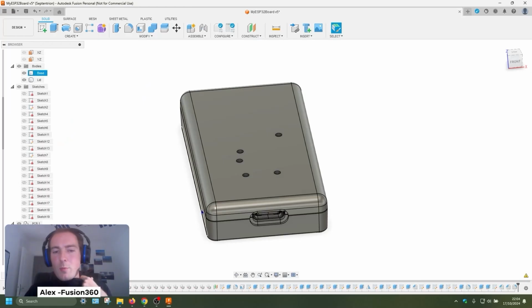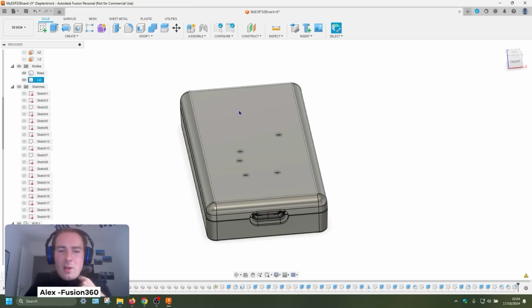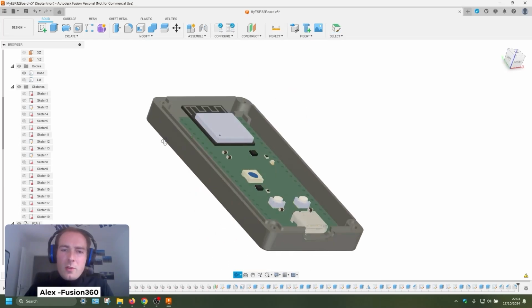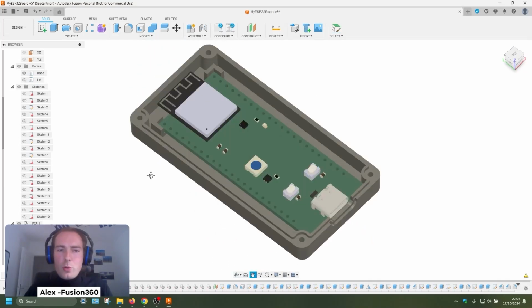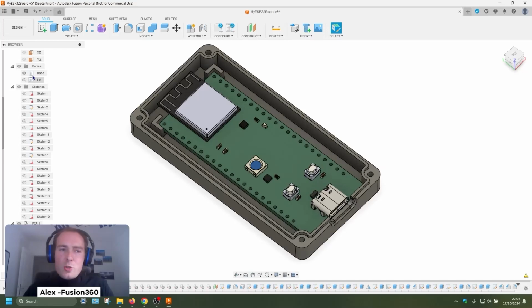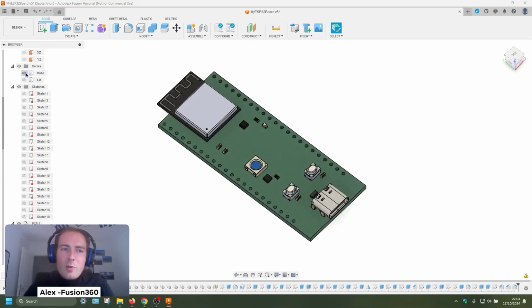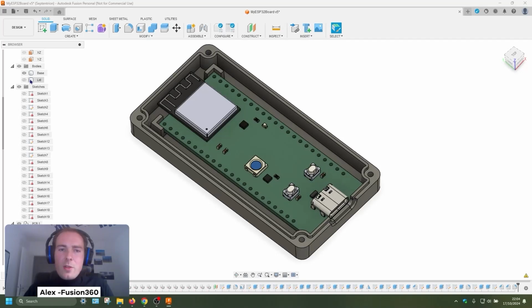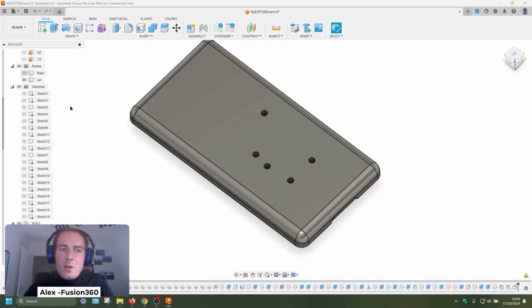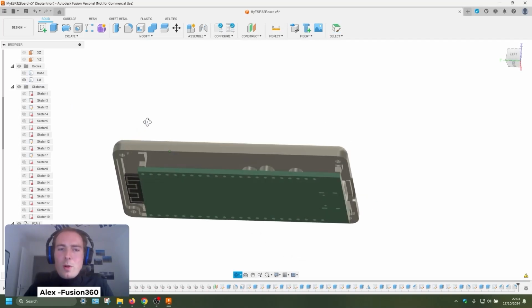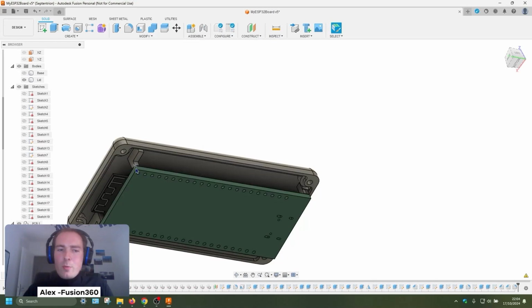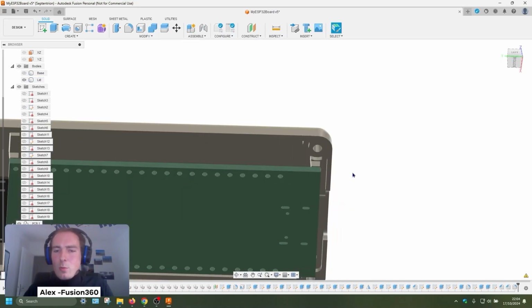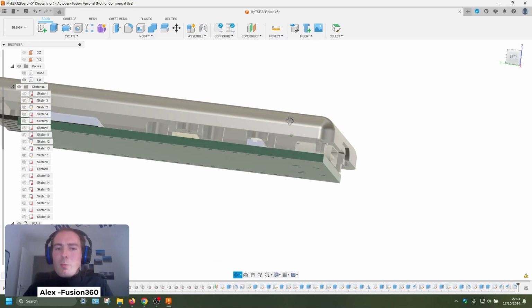So since I had so many problems, I went with an absolutely basic enclosure. The thing that I did focus on is manufacturability, so I made sure there was a purely 2-part mold for each part and nothing else. So that would really represent minimal cost in terms of fabrication, with just 4 screws, and the PCB is held in place via pressure basically between the 2 parts. One of them has hollows and the other one presses the PCB down in there. The concept is at maximal simplicity with just the greatest basics possible.